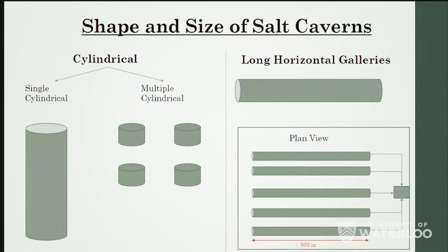Interestingly, for long horizontal caverns, your wellbore actually comes in at one end, like this. And that means that roof falls are not so critical in well impairment for a horizontal cavern as they are for a vertical cavern. So the design parameters are different. And we hope, during our research, to clarify these things somewhat. But remember, we're always dealing with uncertainty at various scales.